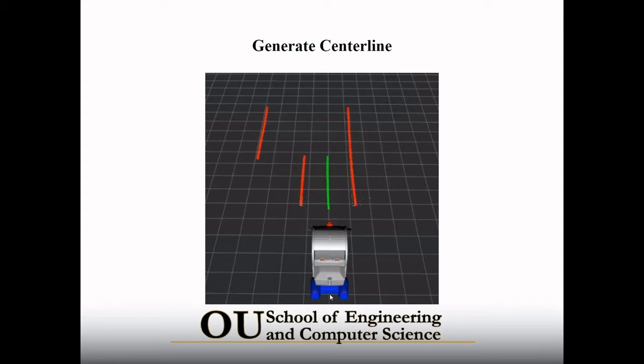The middle center point of the rear axle of the frame represents (0, 0). We have the positive Y, and in front of the car the positive X. So by adding the Y's of these two points, we get the first point, and by continuing to do that we get the green center middle lane that we need the car to follow.